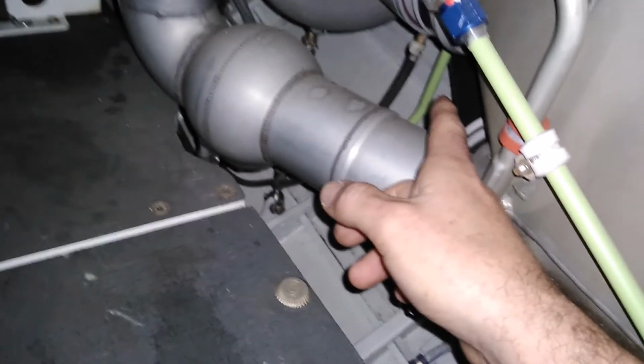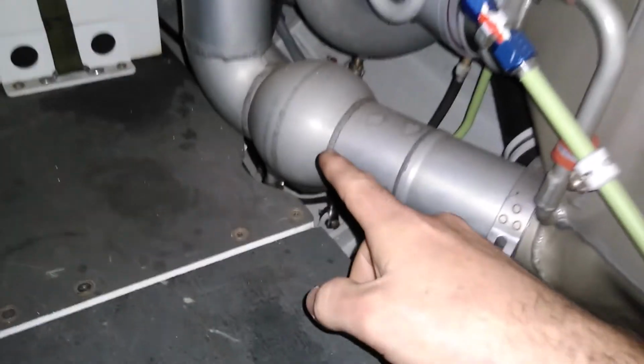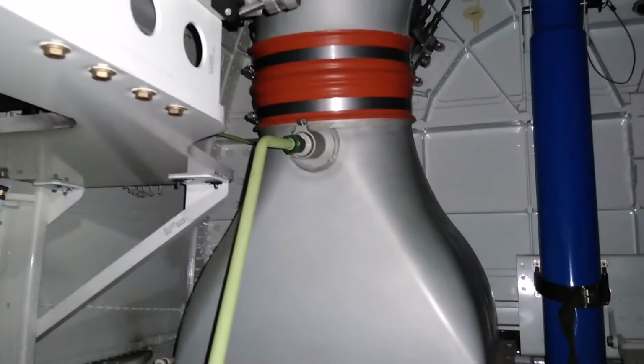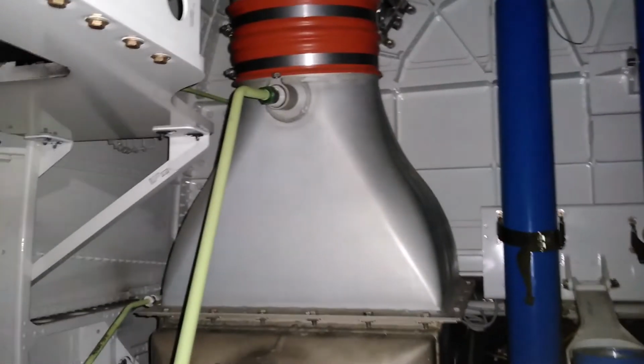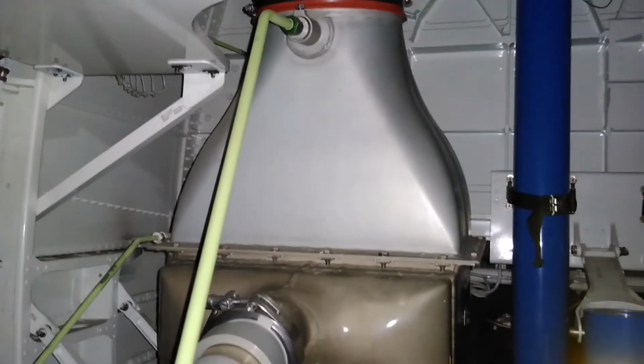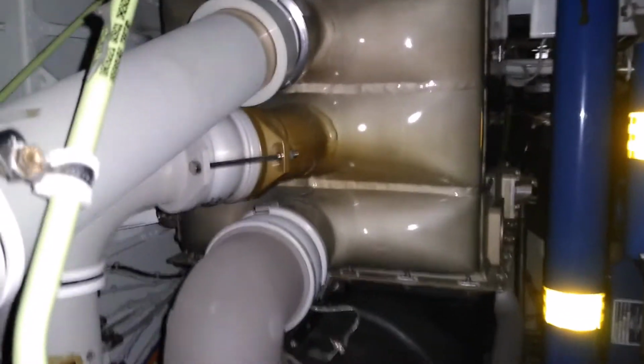and see that green pipe over there? That is a drain from the bottom of this, taking that water through here and taking it up there to spray the water right into the path of the ram air, and now you have a mist of water being sprayed over the heat exchangers.